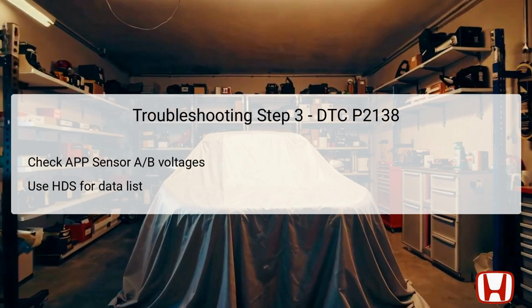The HDS provides a detailed data list showing real-time voltage readings from the sensors. If the voltages are the same, the system could be functioning correctly, redirecting the technician's focus to other troubleshooting steps. However, if there is a noticeable difference in voltage readings, this indicates that further, more specific troubleshooting steps are required to identify the failing component or wiring issue.